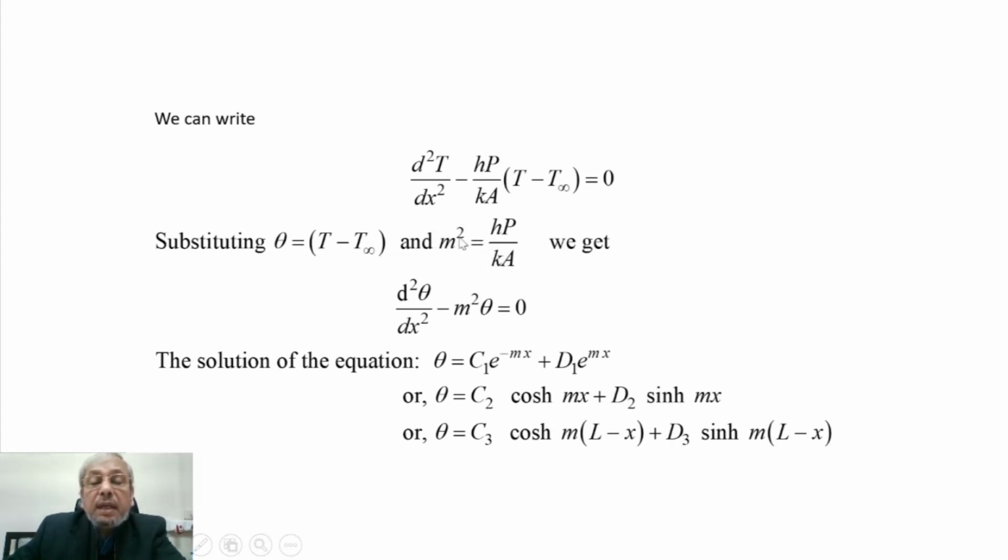m is a parameter which basically comes out of combining these terms, but it has no typical, I would say, physical meaning, but can be interpreted as the ratio of a form of convective resistance and conductive resistance, or conductive resistance and convective resistance, because 1 by h we have to now bring in the denominator and then readjust the terms in such a way that this heat transfer coefficient by conductivity can be expressed that way.